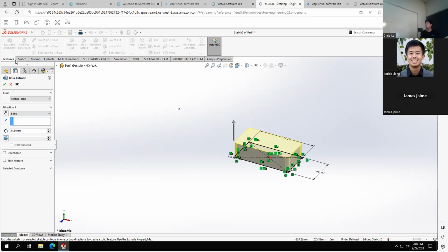Okay. So there are different ways you can extrude this, right? You can do a blind extrude, where it just assumes where you want to extrude it. You can click this arrow to make it go up, or extrude it downwards. There are other ones called up to vertex and up to surface, so I'm extruding from one surface to the other. We're going to use that feature later. Extruding from the midplane. So there's just a bunch of different ways you can extrude this.